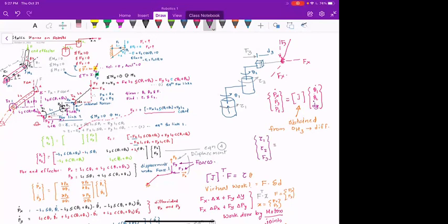You can grab this Jacobian, take the transpose, and multiply this by Fx, Fy, Fz, and you got the joint torques without writing the equations for summation of forces is equal to 0, summation of moment is equal to 0 for all 3 joints.